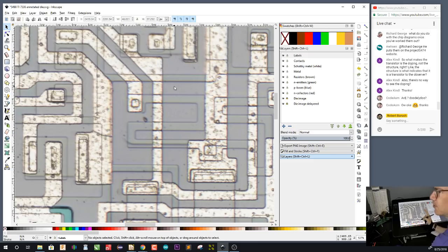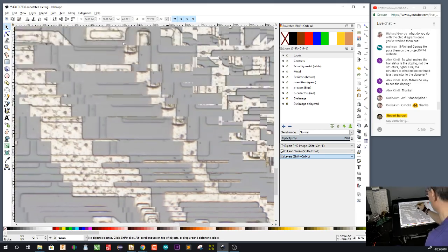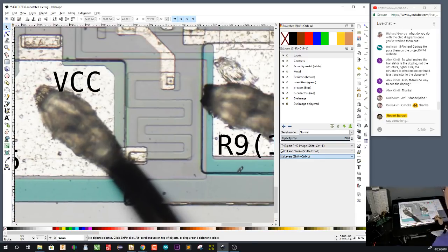And the reason that I made this discovery, and that it's important, is that if you look at these resistors, now somebody mentioned that they got excited because they saw a resistor. So I'm going to go to that resistor right over here. The squiggly bit is a resistor. Now, resistors on TTL chips are made out of strongly p-doped material, because it has to be relatively conductive, but not too conductive. So there's a certain doping that you use, but it's always p-doped.